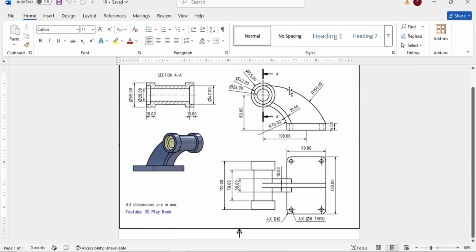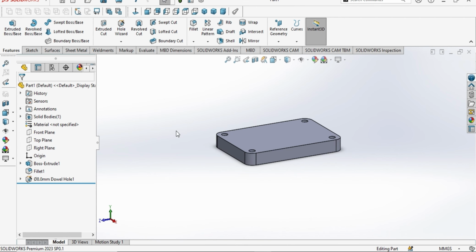Let's apply this feature of radius 150 and radius 70. If we see it from the top, it is given here with the thickness of 10 in the middle of this body, and extrusion for this 8 to 10 millimeter with radius 70 is given here. Look, 30 millimeter. Look, this circular flange is of 30 millimeters. So let's go make this.